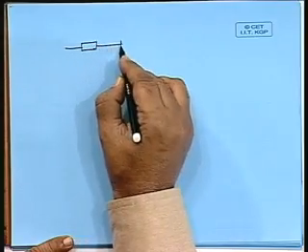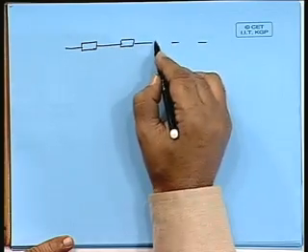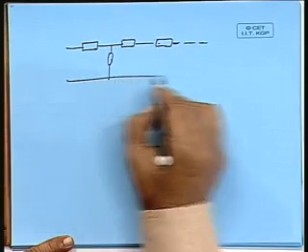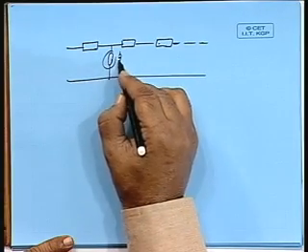Now, a short circuit means what? It should be a series resonance. If I have a series resonance at s equal to j3 and that element is put in shunt, okay. So, you are having an element like this, there are many such elements. In the ladder I create, this element is say an LC combination.